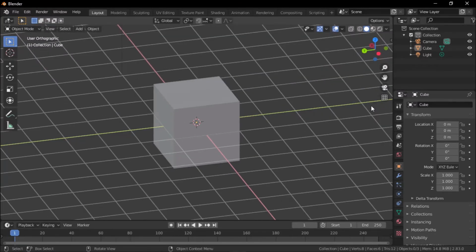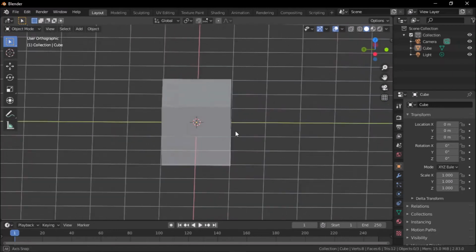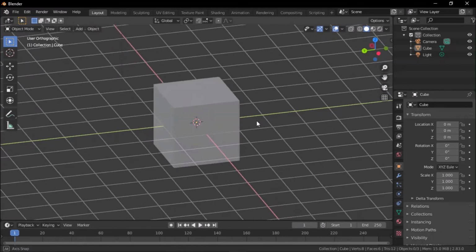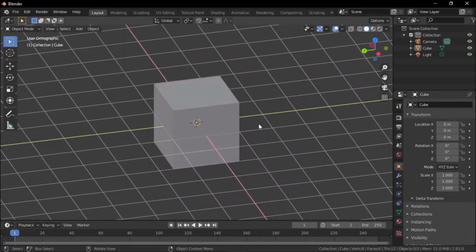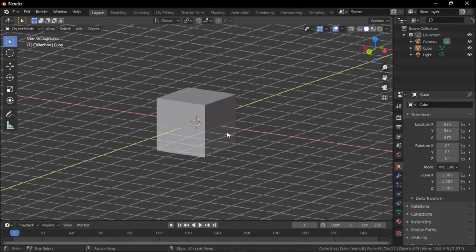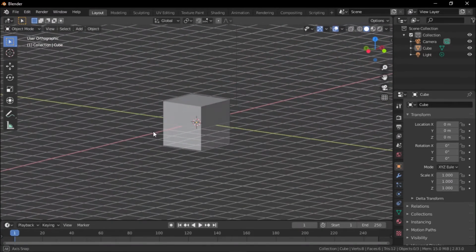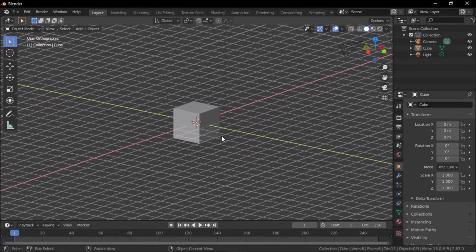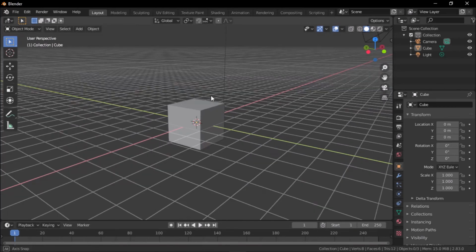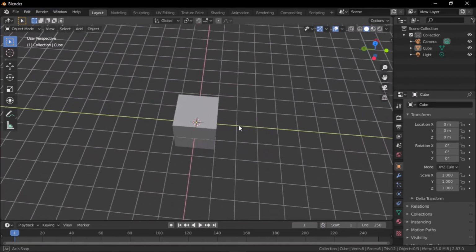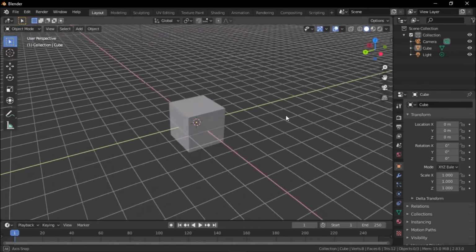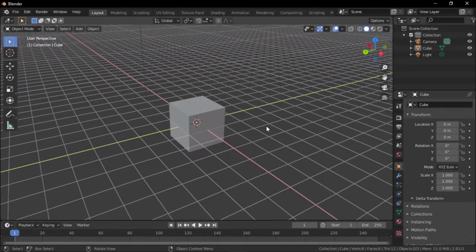But you may be asking, what's the difference between these two modes? Well, perspective mode is a realistic view of 3D objects in your scene, which takes into account how far away objects are from you in how it displays the object. The further away something is, the smaller it gets visually. However, orthographic mode ignores all of that and flattens your world so that no perspective is seen. Everything is angle perfect. This is an unrealistic view, but helps immensely with making models accurate, especially in relation to, say, a 2D concept sketch.